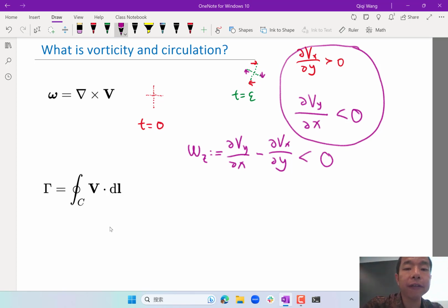Another corollary is if the rotation of these crosses are in the opposite way. So if my cross has been rotated to be like that, which means they are not forming a right angle anymore. Instead, the horizontal is rotated counterclockwise and the vertical is rotated clockwise. And if the angle of the rotations are the same, what does that mean? That means both of them are positive or negative, right? So if you subtract them from the definition of vorticity, you get 0.